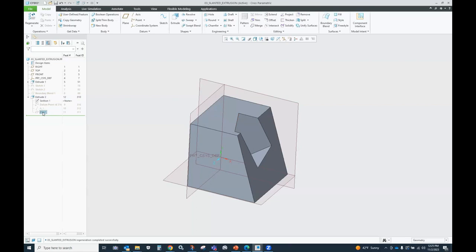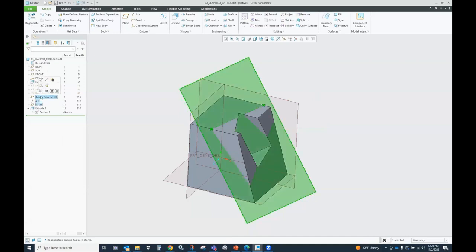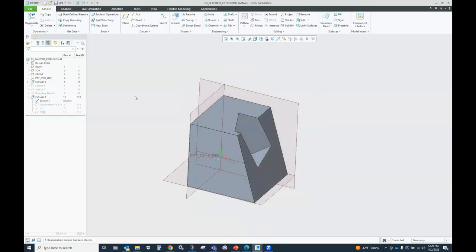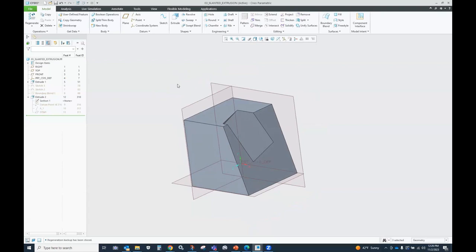So if I take that datum and I drag it out of that feature, boom, you'll see all those datums are there, right? And of course, I see them now on my screen, right? So you can imagine if I did that for every feature that I needed some odd angle, I could have dozens, if not hundreds, of datums. And when I put that in an assembly, I see it all, right? Well, I don't want that. So I'm better off if I just leave that inside that feature and I don't see it in my tree. I don't see it in the view, I'm golden.